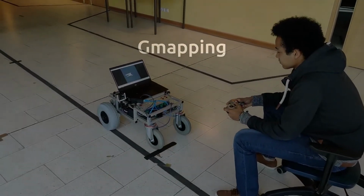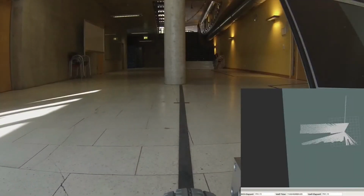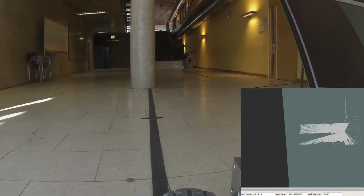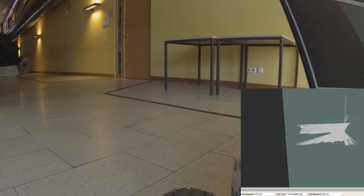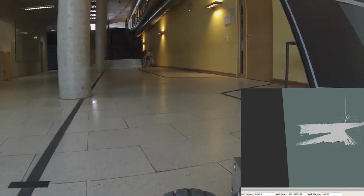The rover, in this case controlled by a human operator, is starting at a position and gets its first laser scan measurements. As it is driving, it explores more and more parts of the unknown environment, and the map expands. The new scans are matched against the existing map to perform localization.